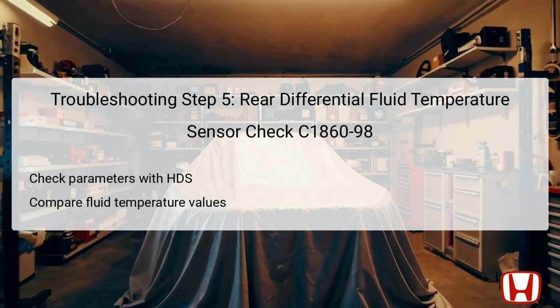If the difference between actual temperature and expected values is significant, it raises concerns regarding the functionality of the temperature sensor. A minimal difference indicates normal operation. However, if discrepancies are found, replacement of the rear differential fluid temperature sensor may be necessary.